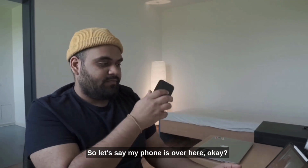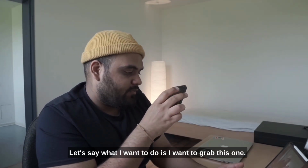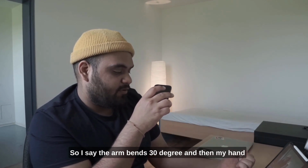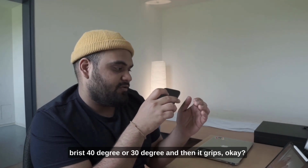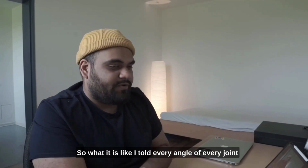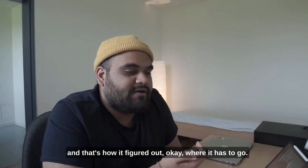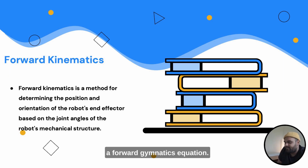So let's say my phone is over here, okay? But what I want to do is grab this phone. So I say my arm bends 30 degrees, okay, and then my hand twists 40 degrees or 30 degrees, and then it grips, and then it has my phone. So I told every angle of every joint, okay, and that's how it figured out where it has to go. And that's what happens in a forward kinematics equation.